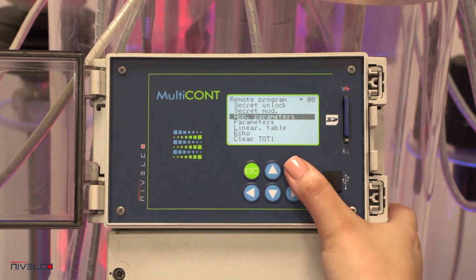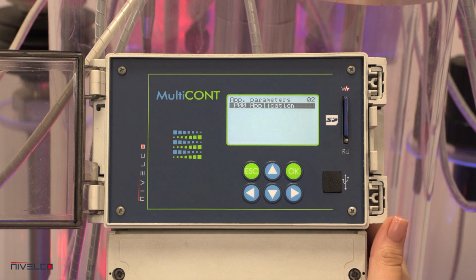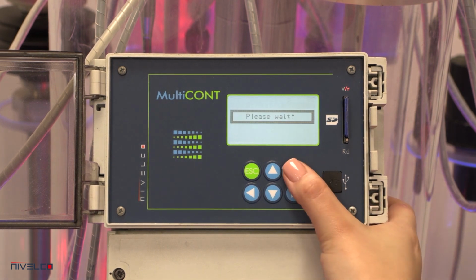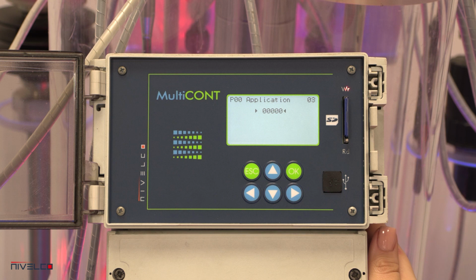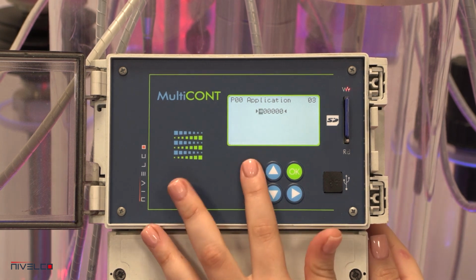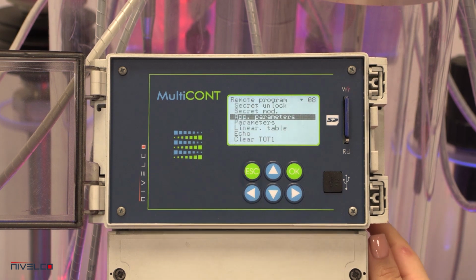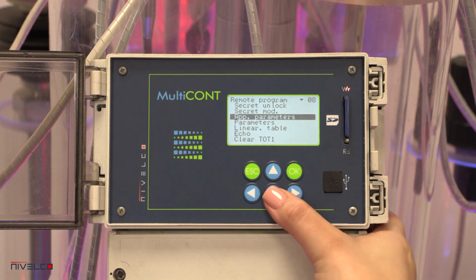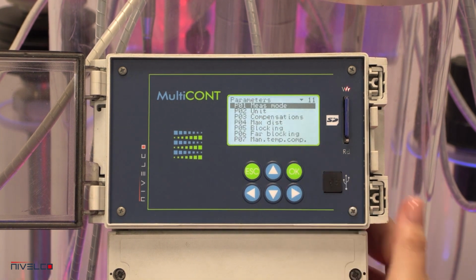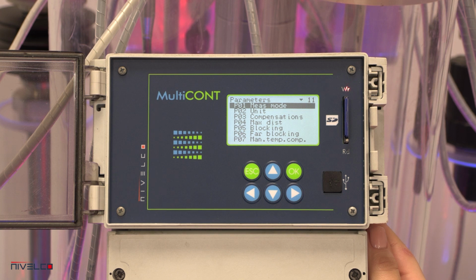The application and measurement units can be selected in the app parameters. The factory default setting is 000, which means metric units, meter, and liquid level measurement respectively. The parameters are device-specific. Read the device programming manual for details, but we'll go over a few essentials here.